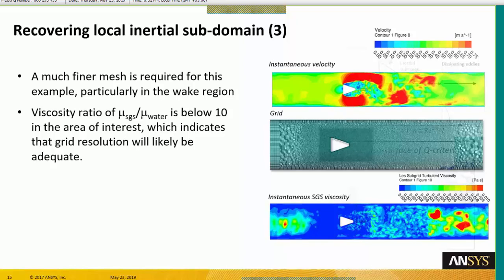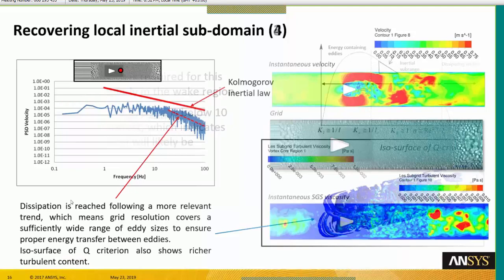So for spatial resolution, some hints, and now for time resolution, you have also some constraints to keep in mind. When you do LES, usually temporal resolution should match or exceed the spatial resolution. So you have some CFL condition, and usually the CFL condition translates to the Courant number. Remember when I was talking about this Courant number for the second lecture on direct computational aeroacoustics, there was a clear difference. The difference was I was not considering the flow velocity but the acoustic speed of the wave. So this is different, so you need to be extremely careful at this point.